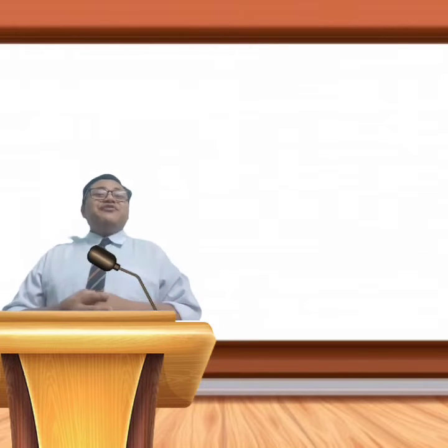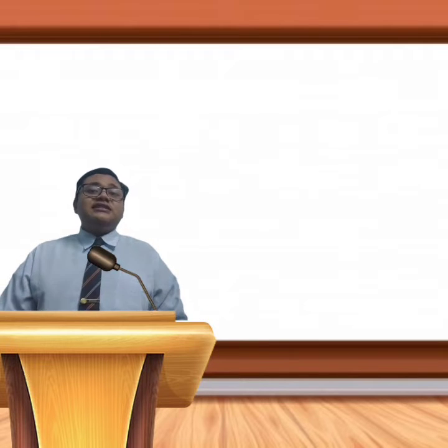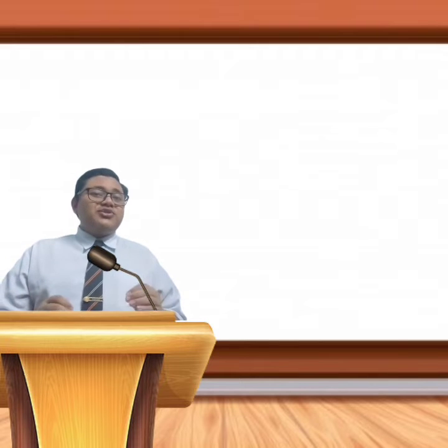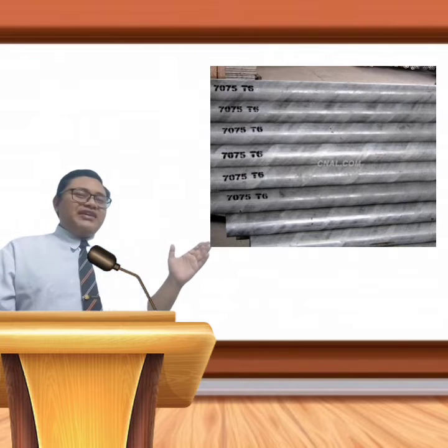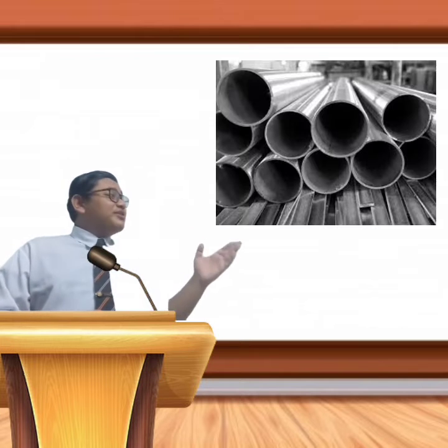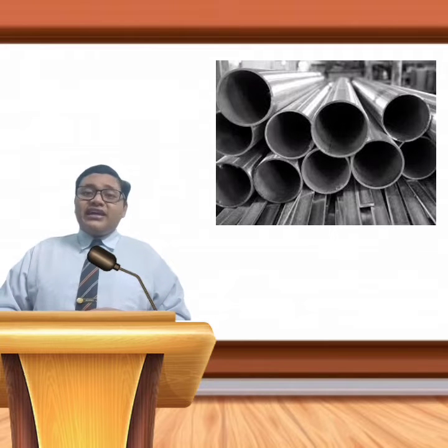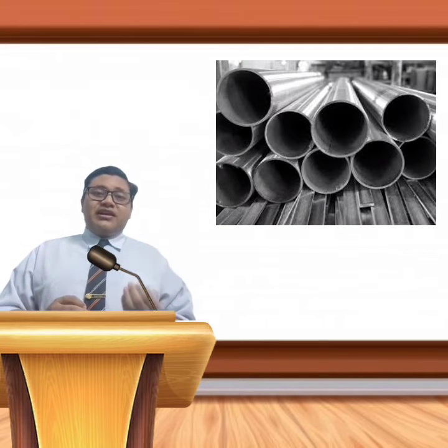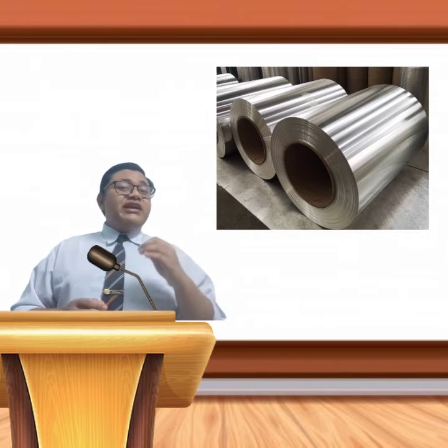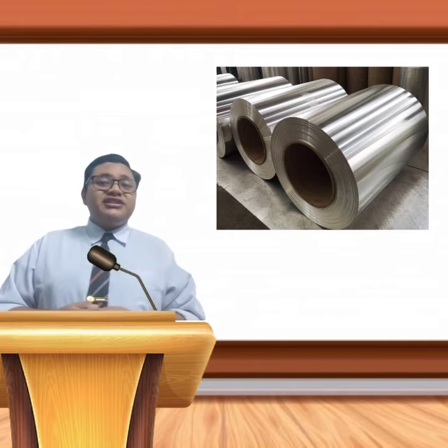Okay, Sarah, thank you for asking me. Well, basically, their specific functions can be applied in certain parts of the aircraft. For example, the most preferred and strongest, aluminium 7075, is used for the main part of the body. Next, aluminium 6061 is the lightest one, suitable for making ideal wings and fuselage for the aircraft. And next, aluminium 2024 is used in making large hydraulic manifolds because it has high strength and fatigue resistance.